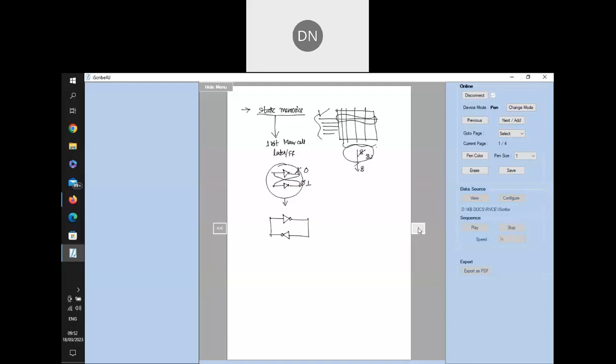Now only when required the cell has to be enabled. If not required, the cell is not to be enabled. We know that the word line, generated by the decoder, will select a particular word. When it selects a particular word, a particular cell in that word also gets selected. To enable or disable the cell, two transistors are present at both the outputs, the complemented output and the uncomplemented output, Q and Q bar. These are CMOS transistors.